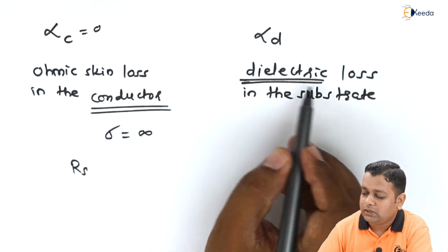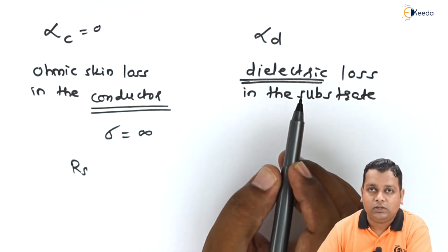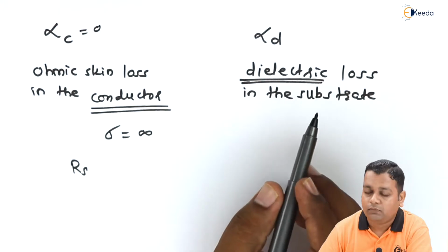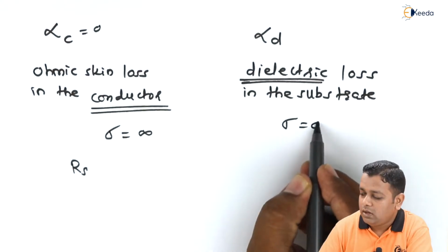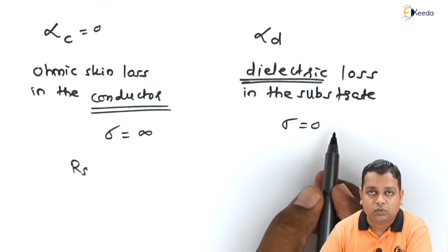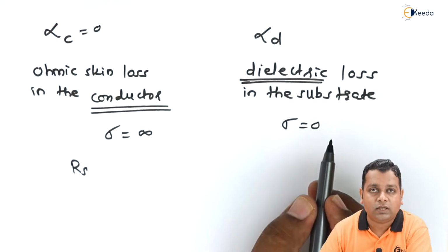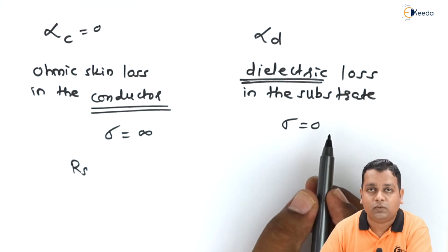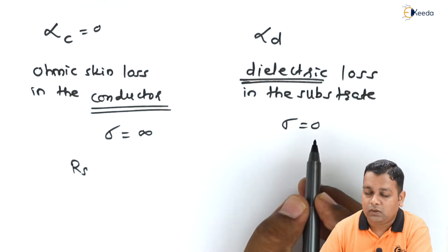In a similar fashion, the dielectric should be a perfect insulator, so it should not allow the passage of conductivity. Conductivity ideally should be equal to 0, but practically there are a certain amount of charge carriers at a very minority level that can support a conductivity value.